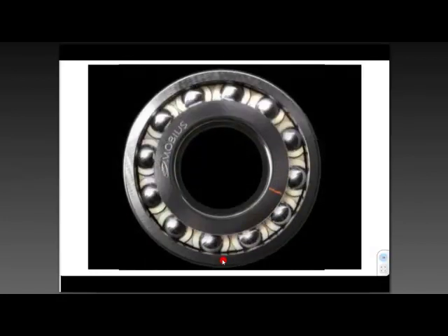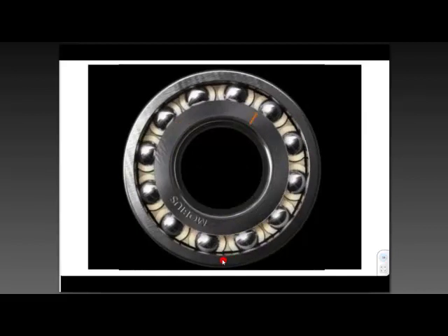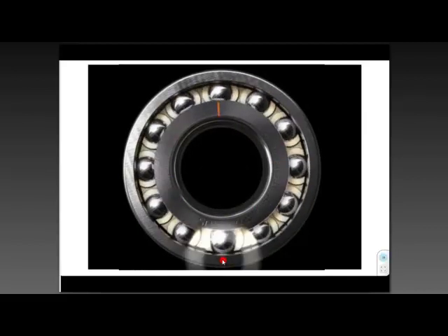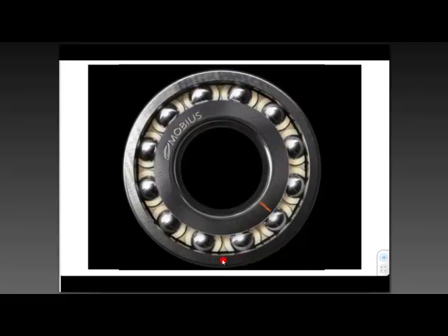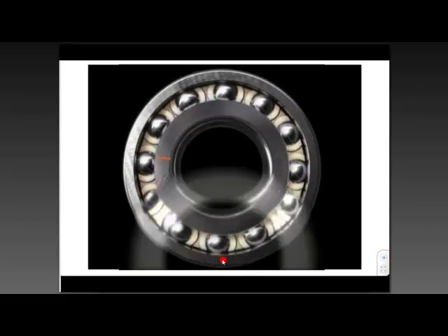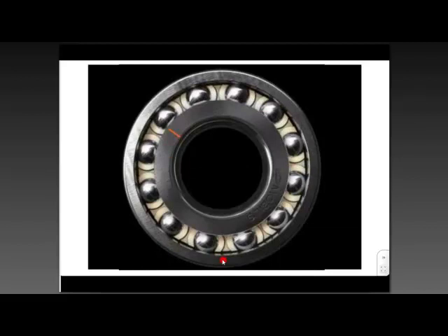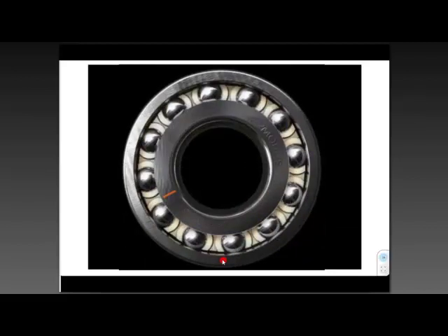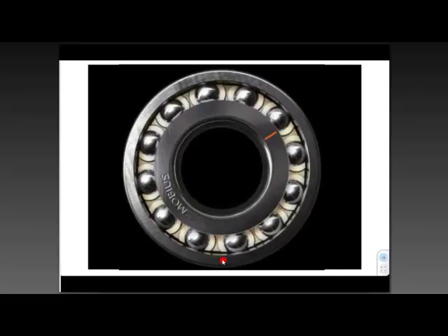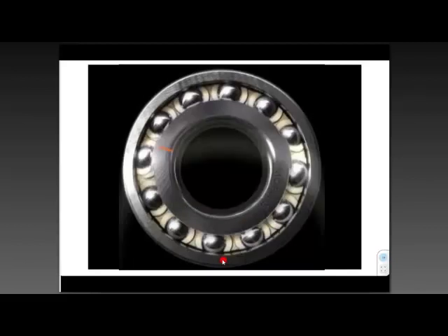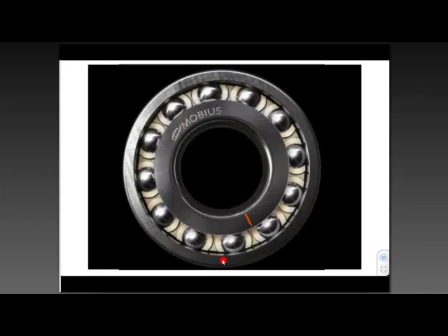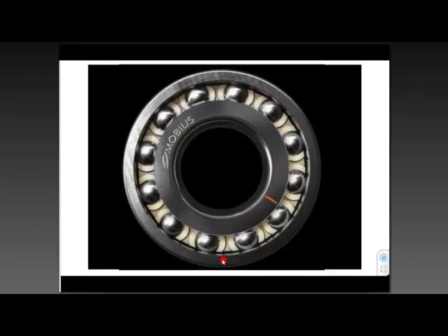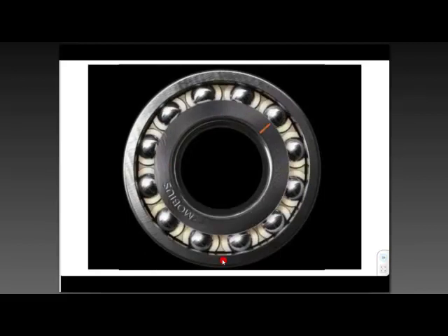But when there is only slight damage to the bearing, the simple way to put it is that the vibration in the normal frequency range where people normally measure will not change. You will not see that there is a fault developing in the bearing. Instead, what we want to do is listen to the very high frequency vibration, and I'll mention a bit more about that in a sec. So that's if there was a fault on the outer race.